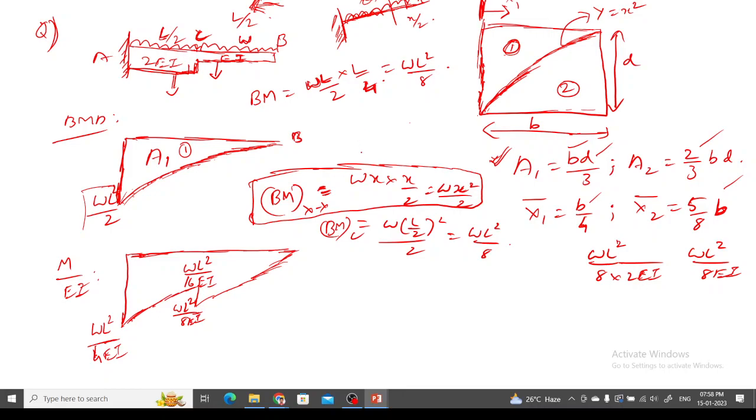See, this bending moment equation is valid all through the beam. The only variation is that I should put the x value from this side. Whereas if I am taking from the left hand side, I have to calculate the moment reaction as well as the vertical reaction, and then I have a uniformly distributed load also. So I have to take the individual effects of all these three things together to find out the bending moment.